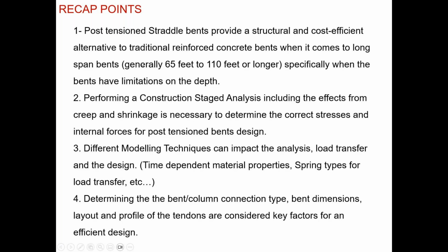Also, performing a construction staged analysis is considered really important, especially to include the effects from creep and shrinkage, and to be able to determine the correct and representative stresses and internal forces for the post-tension bend design. I would say there are different modeling techniques that can also impact the analysis and the load transfer. So you want to make sure what time-dependent material properties you are using, what spring types you are using, and for the load transfer, this is really important.